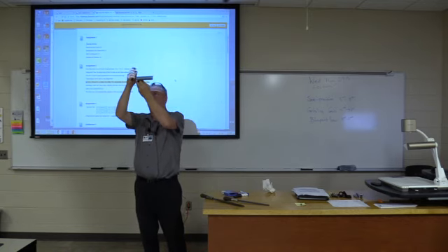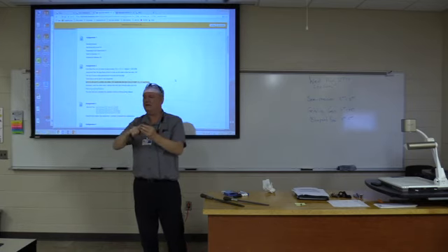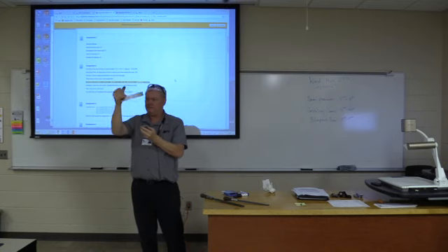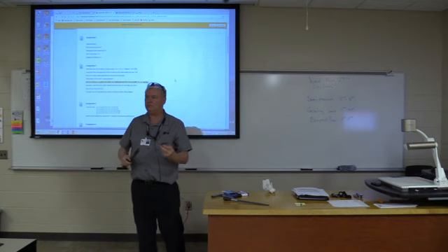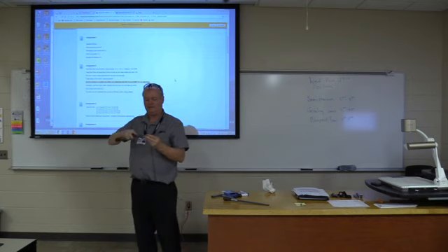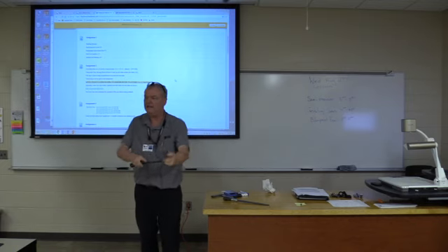And what we can do is we'll eventually just run this. This is a machinist square. We have 2 of them in back. But as you hold this up to the light, you'll want to not see any sort of cracks between this and the surface. So although I'm holding it in my hand, the best way to do it is in a vise. And so if the piece is like this, you're going to file across the face like so. You're going to have both hands on it, and you're going to be working it like that.